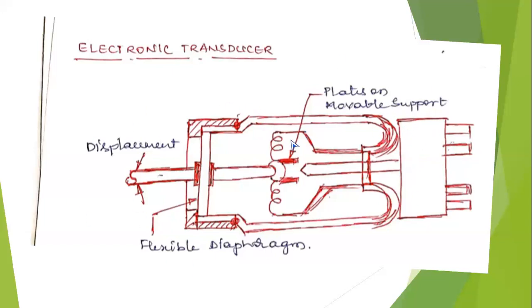The entire electronic transducer is covered in a stainless steel shell, and this rod is connected to the terminals. Connect these 4 terminals to the milliammeter. Then start moving the plunger on the surface of the surface plate or granite block.